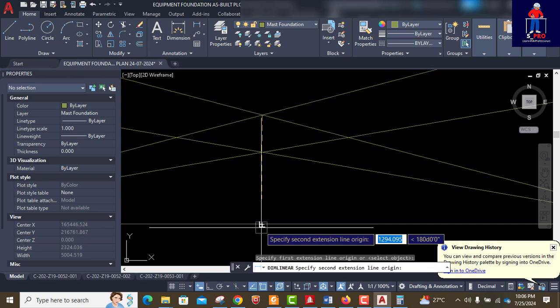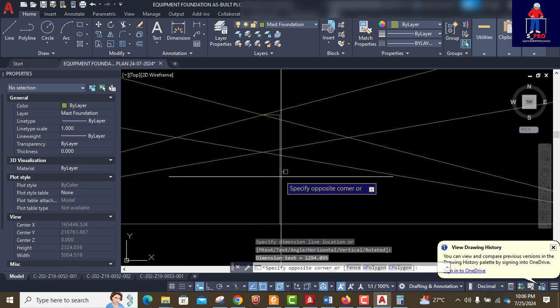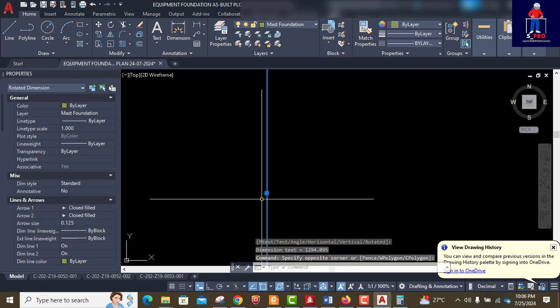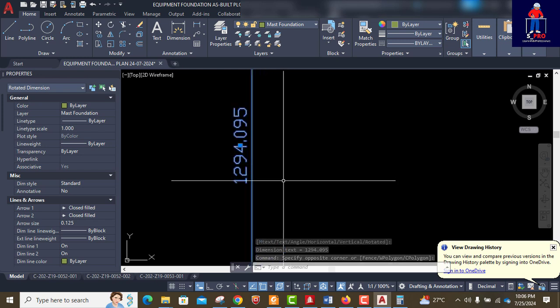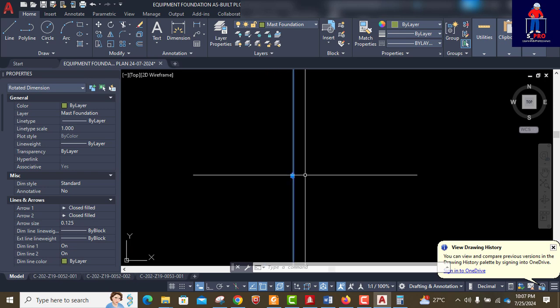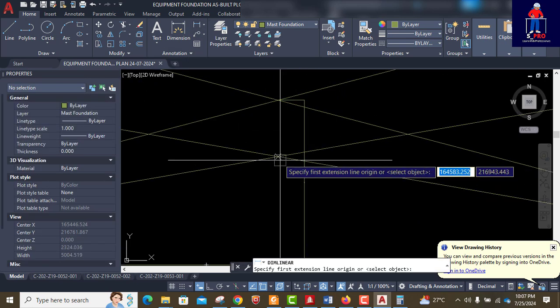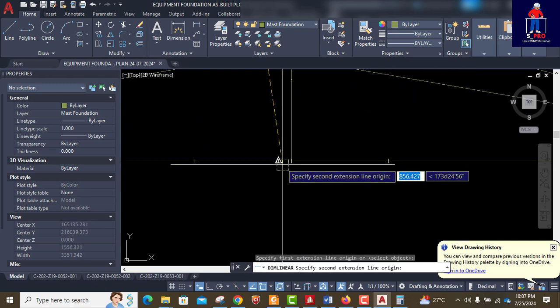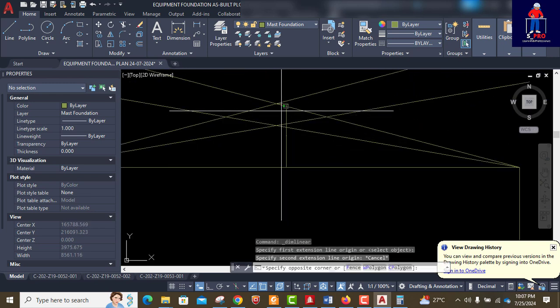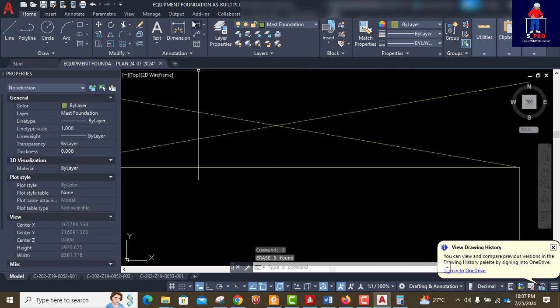Assuming I'm using this, what I have is 1294. I wouldn't like to make the roof go too high, make the structure go too high. That will expose it more to wind actions. So I would just use the gentle slope, this one that is 10 degrees.